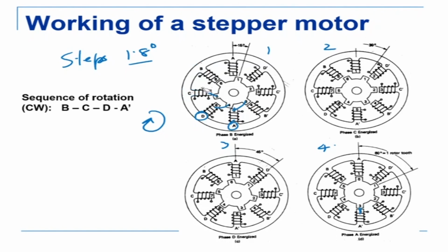Now, how micro stepping is done is if you apply different voltages to these two coils in some ratio. Say V1 by V2 has some ratio which is A. So if V1 is greater than V2, then this tooth will go and stop somewhere in between, but more towards V1. So by controlling this ratio of V1 by V2, we can position the poles somewhere in between also in micro steps. And in micro steps, they can go up to very, very small steps. Say 0.1 degree it is possible to go with a micro stepping motor.